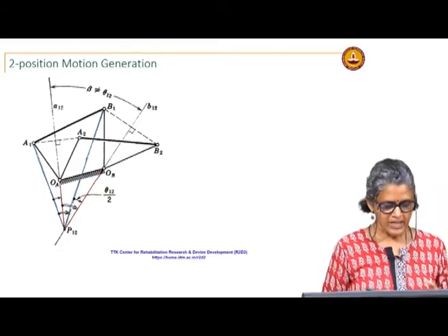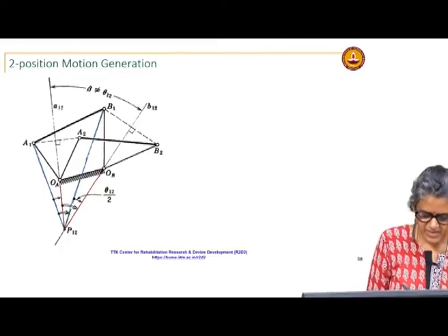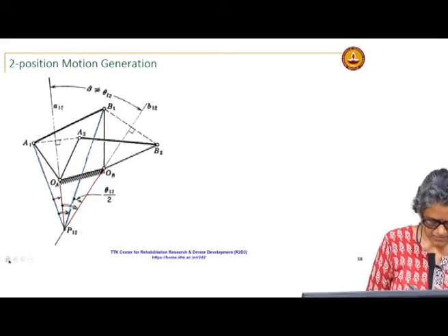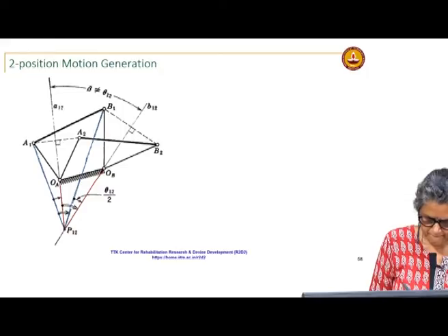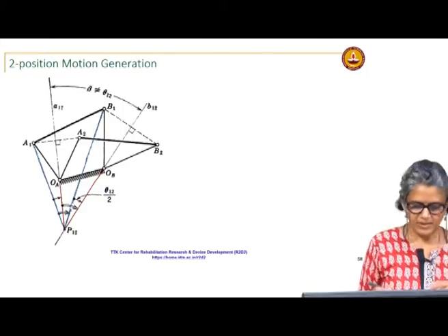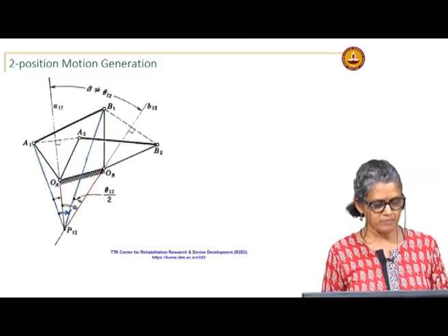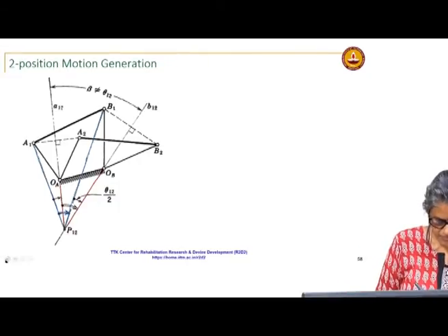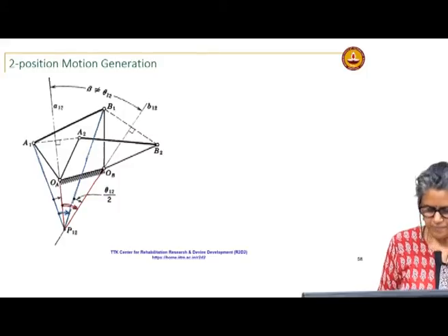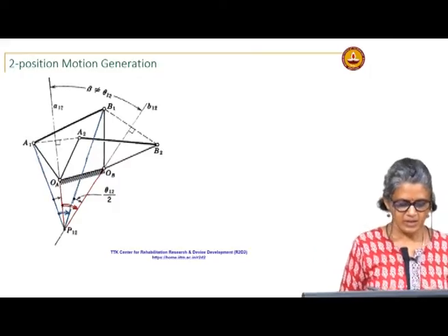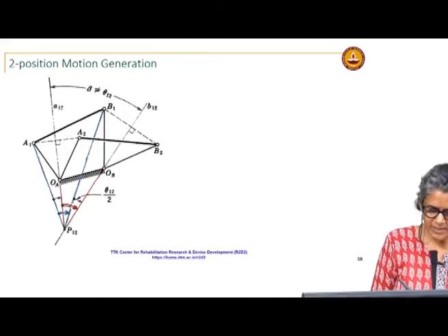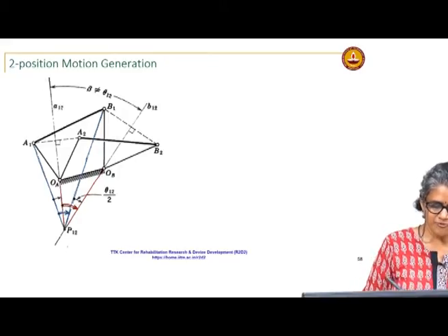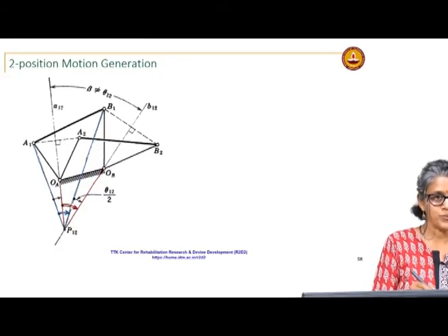Okay. So, I can say this here is the angle subtended by the coupler at the pole. Okay. And then I have OA OB subtending this angle at the pole. Now, tell me, this is the perpendicular bisector of A1 A2. Okay.